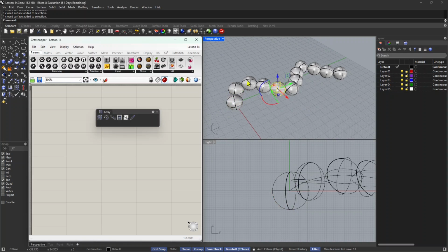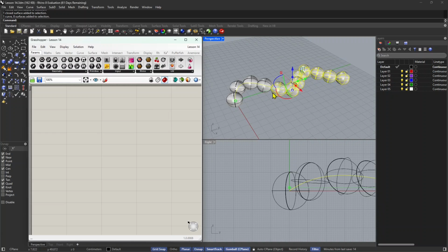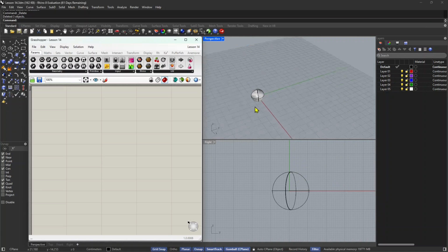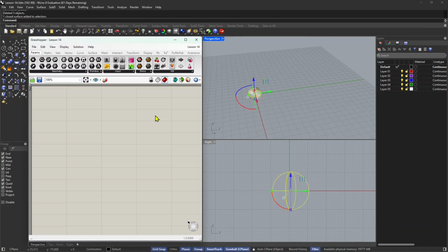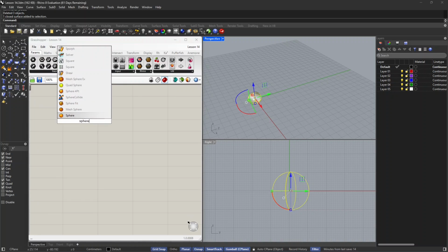So if I want to change the radius here or anything else, I need to actually resize or change the points' position. So it's not really great when you have something complex to build, and also if you change operation, if you close and you reopen, you cannot retrieve those steps. So this is why Grasshopper is very useful, because everything will stay visually in the canvas here, so we can always go back and forward. We can do reversible operations.